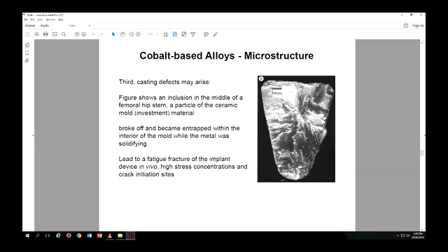This is another thing that's happened. Here, there are some defects right in the middle. What's happening is probably it has started to cool down from the boundaries, obviously. If you have it in the mold, it cools down from the boundaries, and as it goes to the middle, it forms some defects. It's not a uniform cooling down. That's why it's not very desirable or strong.